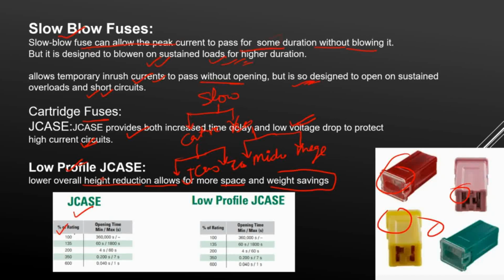So here also, if you see the percentage of rating and the opening time of the fuses. Okay, so if someone asks you one question, that tell me how much time it will take for a fuse to blow, how will you respond to this question? You cannot say that this many seconds. It depends on how much percentage of rating the current is flowing in that particular fuse.